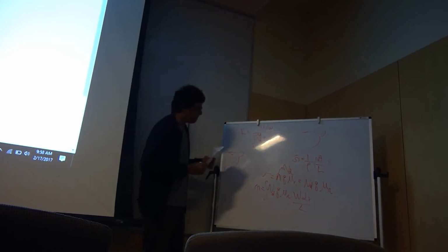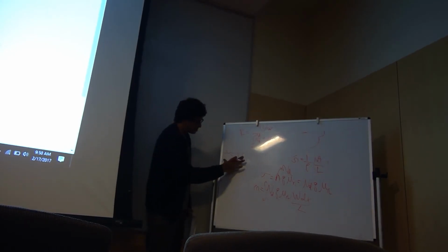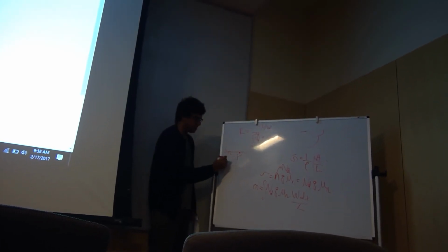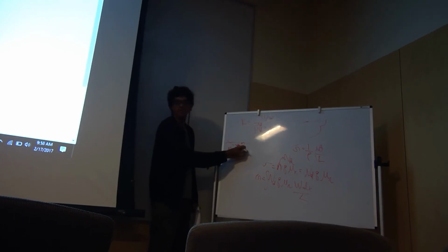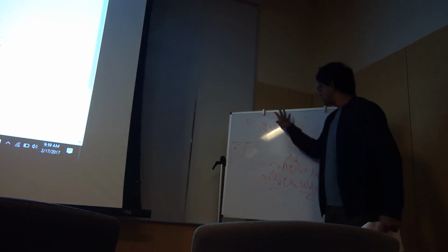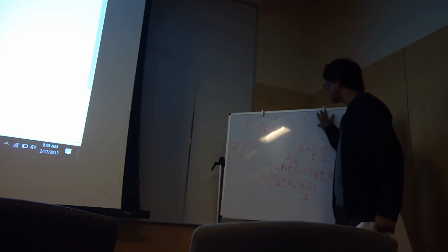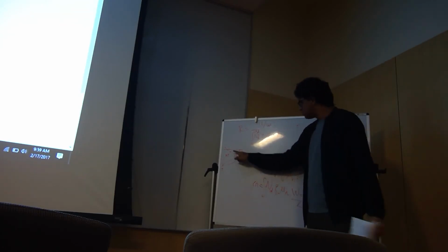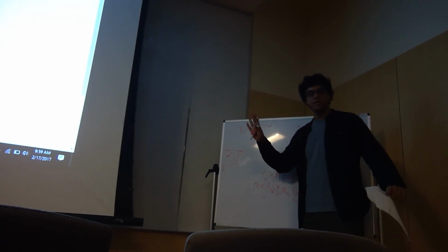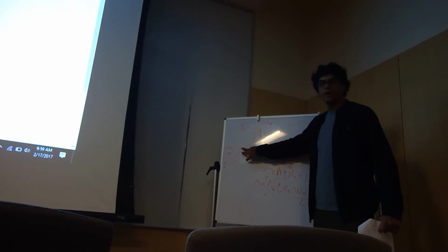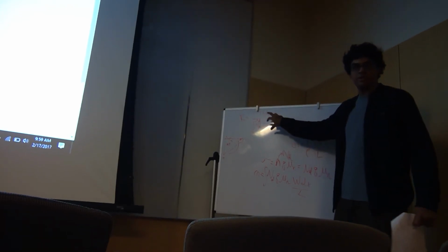Now, this resistance is the series of this region plus this region, because this is n minus and this is n plus. So this has a resistance and this has a resistance as well. So it's actually this term plus another term for the resistance. It's just a series of two resistors. Another term similar to this, but with a different doping for this region. Now, like you said, you can assume this region is so heavily doped that the resistance is almost zero, so you can just figure out what your doping and profile for this region alone has to be by using a formula similar to this.